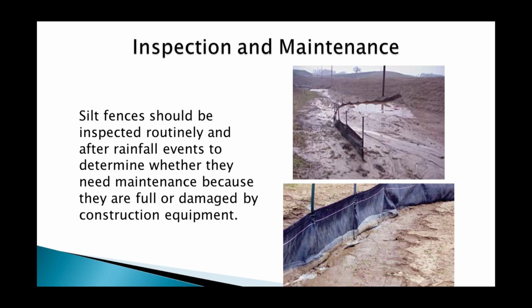On the bottom slide, on the right-hand side, you'll see a silt fence where the runoff is running along the upper side of the silt fence and eroding away the bottom of the silt fence.